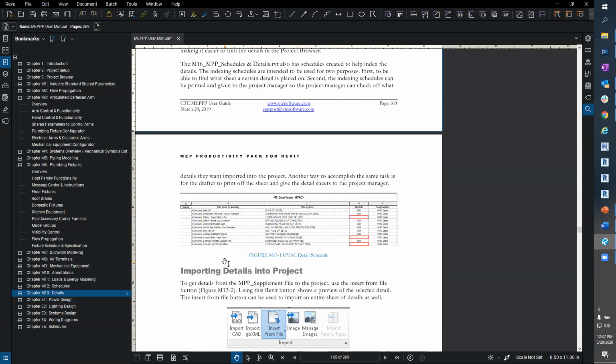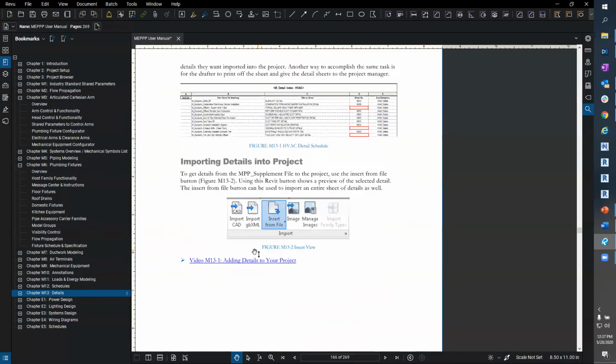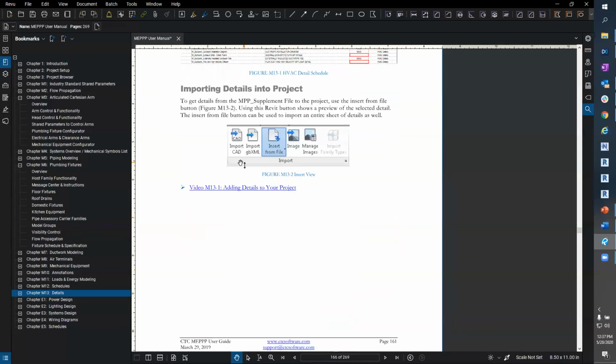The benefit to having Revit details rather than what we used to do, where we dive into AutoCAD, try to bring that over and either link it, or import it and explode it and clean it up a little bit, is that the Revit details are already clean, clear, and ready to go. Just go to the Insert tab and transfer them right across and bring over what you need, as opposed to a huge chunk and killing your model at that point. So those are some of the basic things that are out here as well.